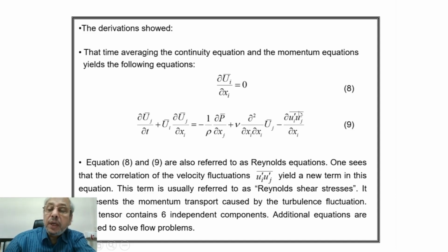But when we express this in terms of the velocity gradients, that means shear stresses, we will get nu t. So in terms of number of equations and number of unknowns, again we will have a balance, but nu t is not known. So the entire challenge will be to find out nu t. It is not a fluid property, so it is not known a priori.